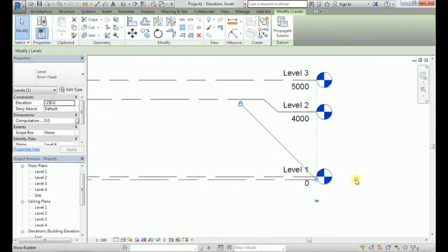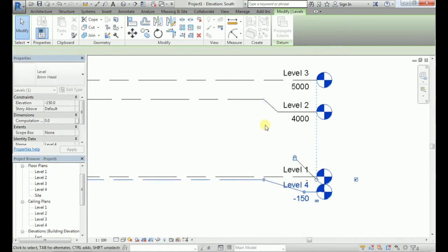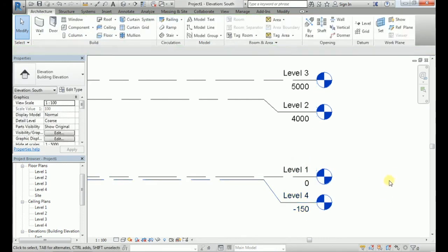Like I said before, you can bring up the annotation using this box, and you can move these. As you see, that dashed line appears to let you know that it's uniform with level 2. Then you can move it down so it doesn't overlap the level 1 text.